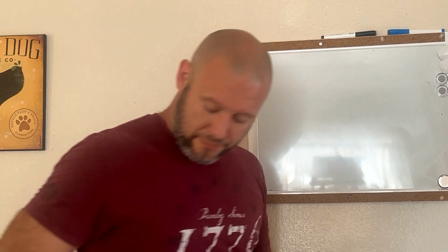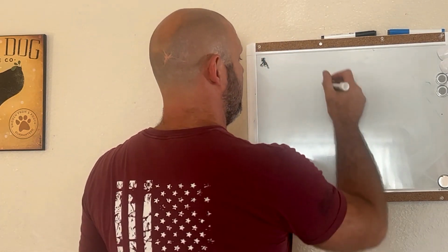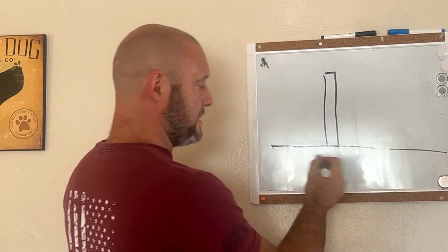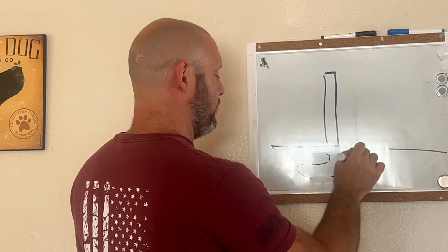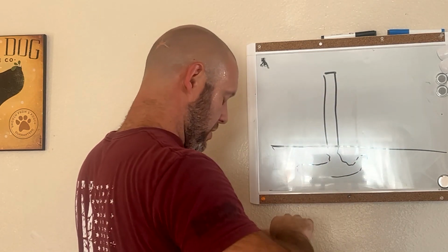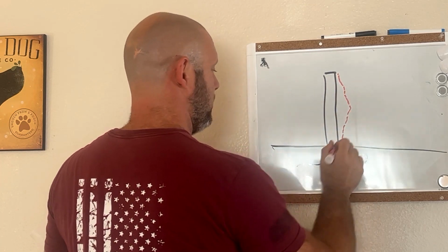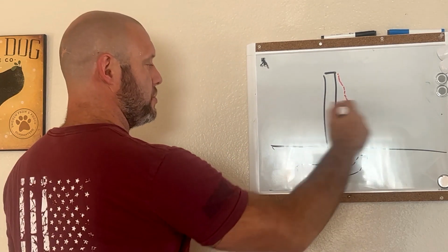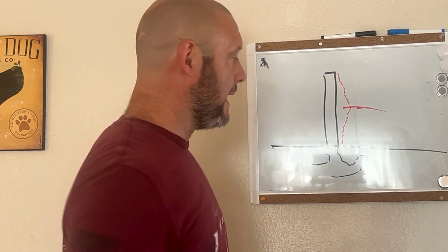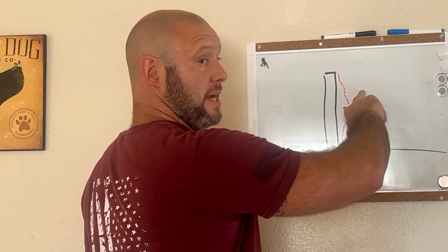If I look at the side of a retaining wall, and it looks like my belly right now. Anyway, right, let's say this is the earth. I can't see underneath. I don't know what kind of footing this guy has at all, right? But if I look at the retaining wall and it's starting to buckle, and it looks like I got a little belly sticking out, it usually has a crack right along that seam right there, right? Especially CMU walls or something like that. You're probably going to want to straighten it using those tieback anchors if you get a chance, right? That helps increase it.